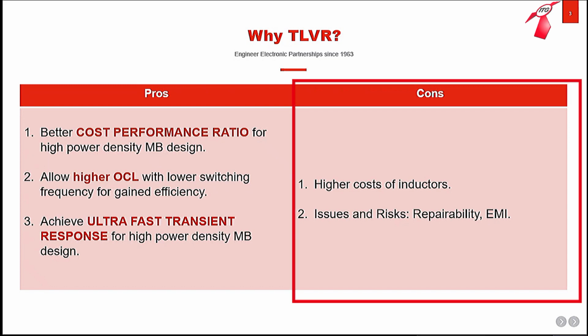Its cons will be higher cost on inductor by itself, since this is a coupled inductor. But due to the capacitor reducing, it will still save on the overall BOM cost. Second, TLVR is harder to get repaired once it has a problem, and higher risk with EMI issue.